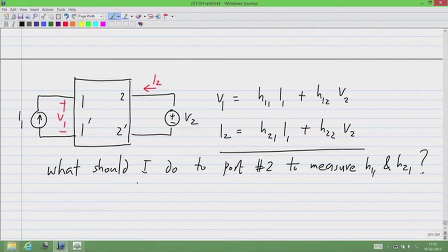So clearly it is short circuited. If you set a voltage to be 0, that means it is short circuited. Actually, there is some confusion here. Somebody responded saying in open circuit voltage will be 0. That's not correct. If you have an open circuit between 2 points, there can be any voltage between those 2 points, but there can be no current. So a 0 voltage means a short circuit, 0 voltage source, and a 0 current source means an open circuit.